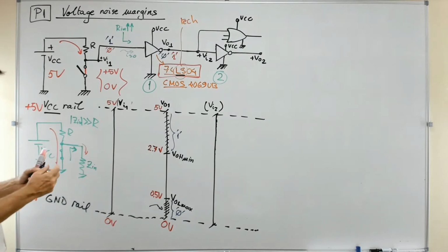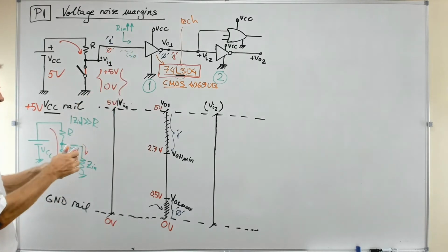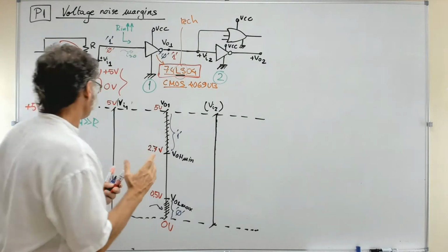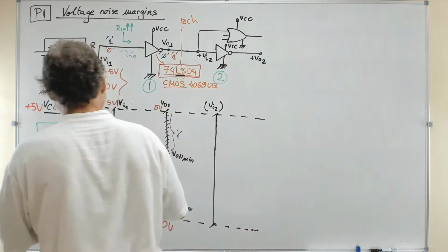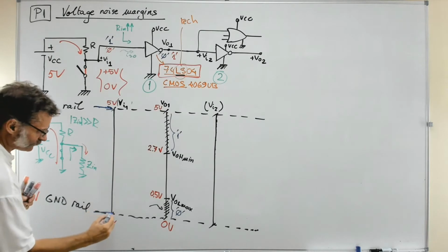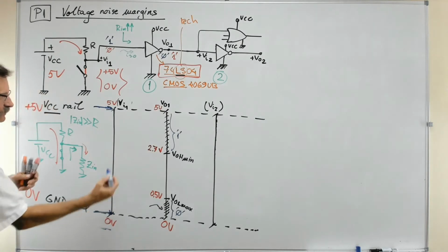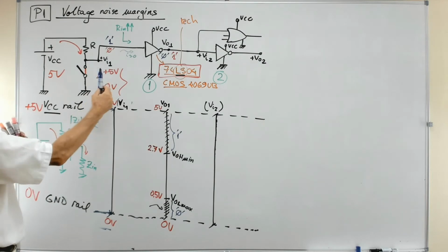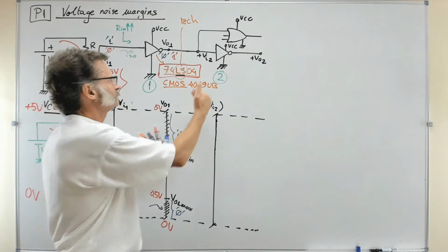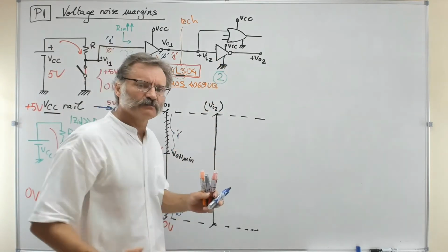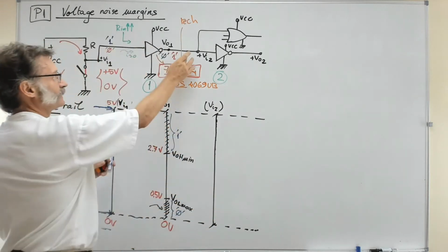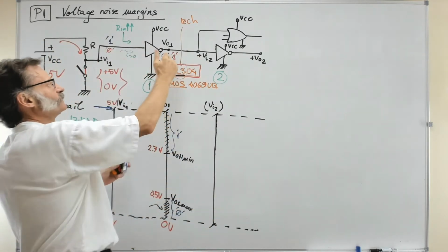But you see, here at the input of this gate, the gate number 1, it is clear that you are driving this very well with a 5 when 1 and 0 when 0, because the voltages are generated from a real chip, from a real switch like this. But now look at where the input voltages of this second gate are going to come from. Well, this is very clear. It is the output from the first gate.